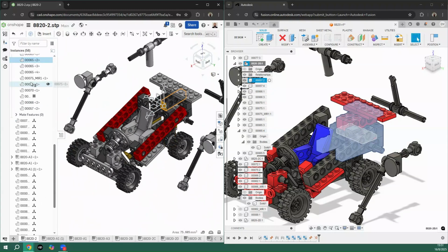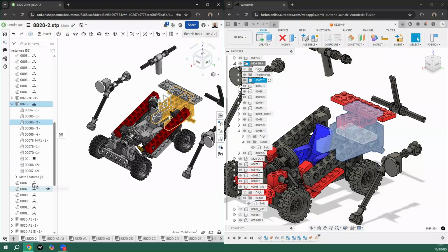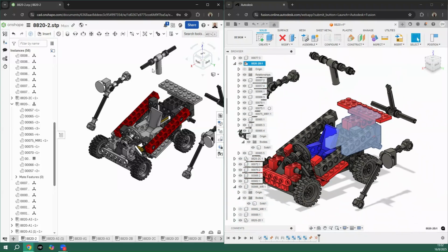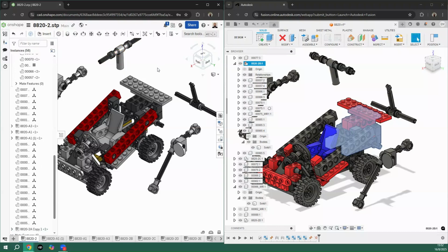So for example, in this one, as you can see, here is the subassembly. The subassembly appears as fixed, but in reality, what I had to do is fix a part of the subassembly inside the top level assembly, so it is not going to move. Let me check. There is another difference here that was important to highlight. As I was not able to make groups from parts that are inside the subassembly, I had to create a copy of this assembly and have them separately, so they can have separate movement in between them. Why is this thing moving?